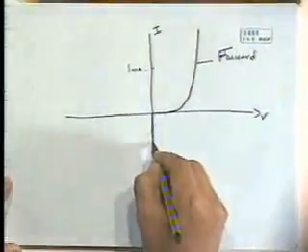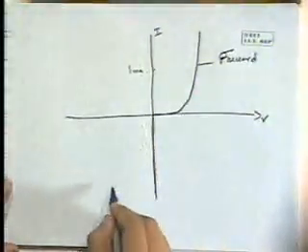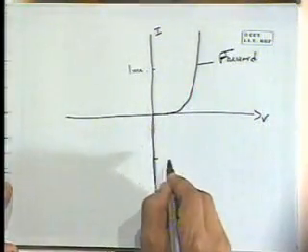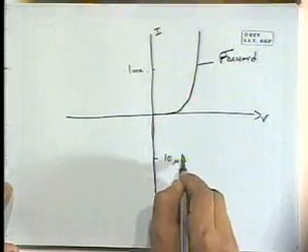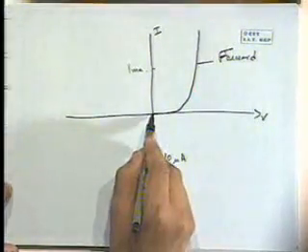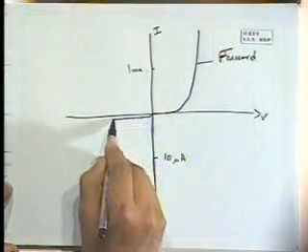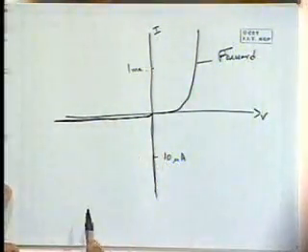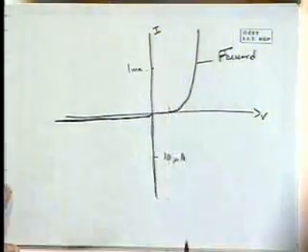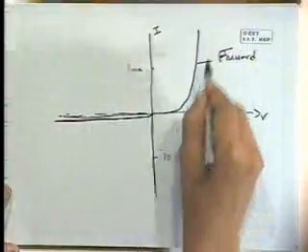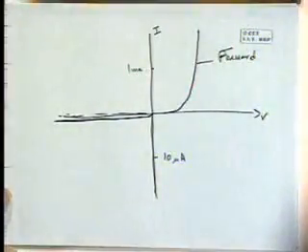In the reverse direction, I'm changing the scale, though I'm plotting it on the same diagram. We are talking of, say, over here is 10 microamps, just to show on the same scale the magnitude difference. Nanoamp kind of currents flow in the reverse direction, and milliamps in the forward direction.